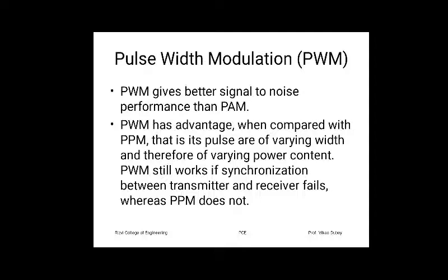But the PWM has some disadvantages: the width is going to change, so obviously the power contained in each pulse will be different. So PWM has a disadvantage when compared with the PPM, that is, its pulses are of varying width and therefore of varying power content.